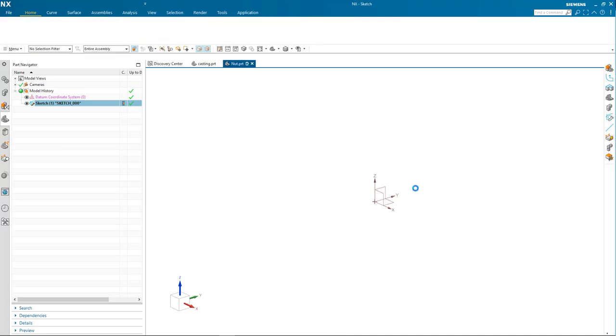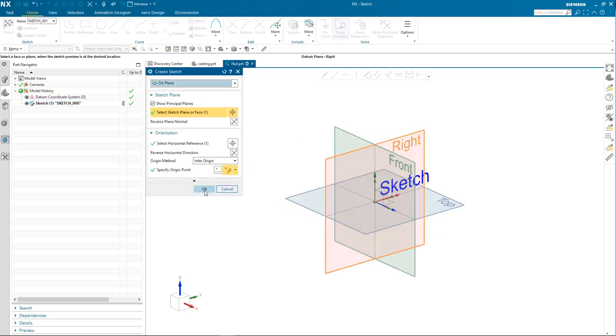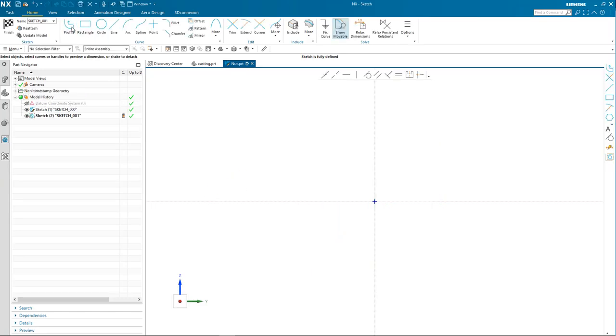This simple demonstration is part of our jack screw. So I've already created a file. In this case, we're creating a particular nut as part of the assembly. I'm going to do the same thing, start it from a sketch, and then create a center line as a reference.